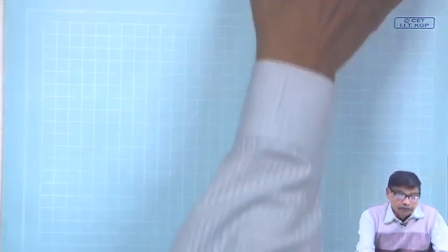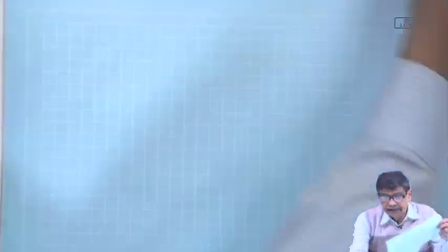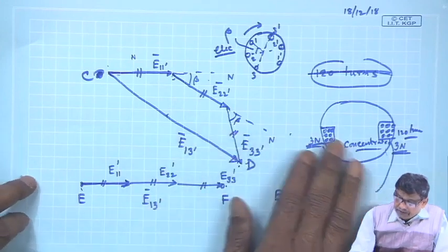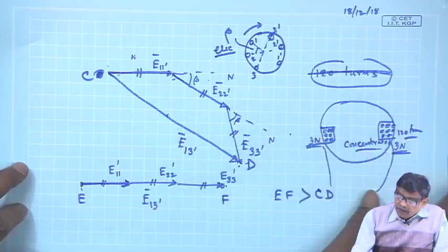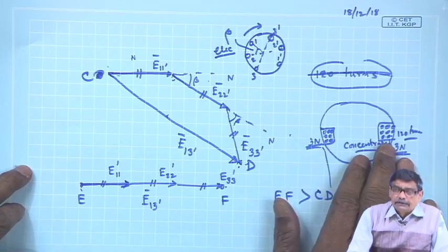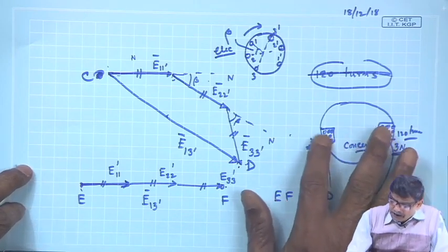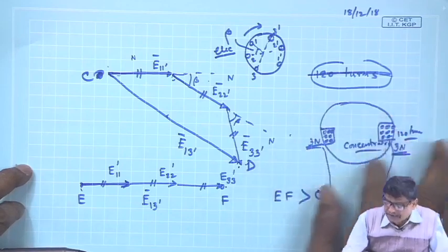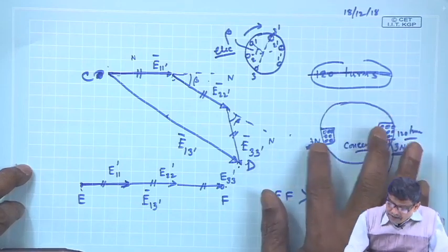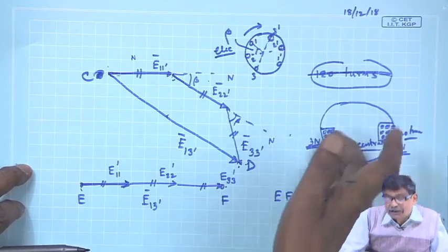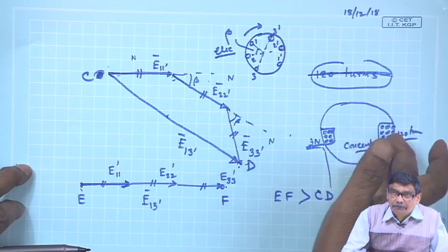Now, coming back to where I left in the last class, the coils will be distributed or concentrated. Concentrated is not wanted for many reasons. If you accommodate many turns in a pair of slots, the rest of the place remains unutilized, and there are restrictions on how many conductors you can put in a particular slot.